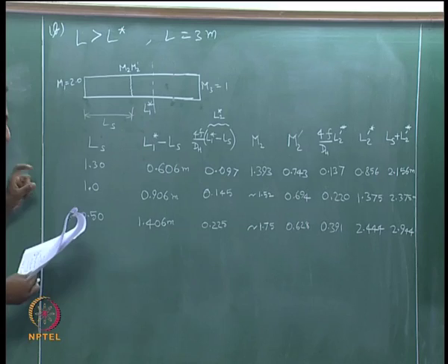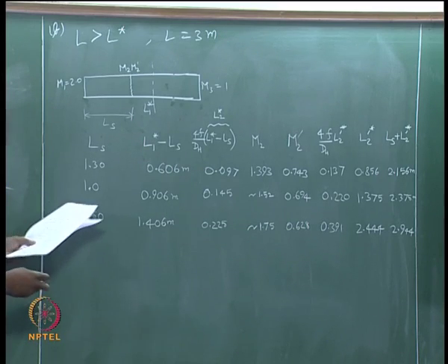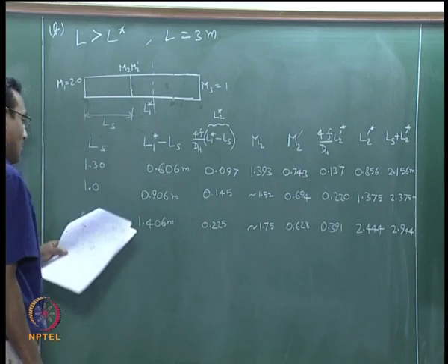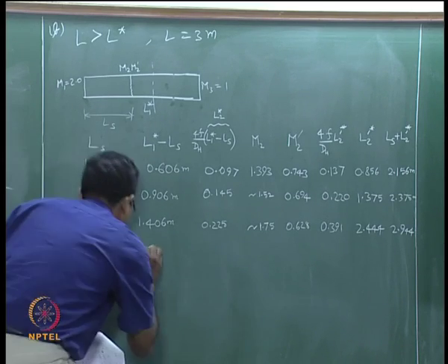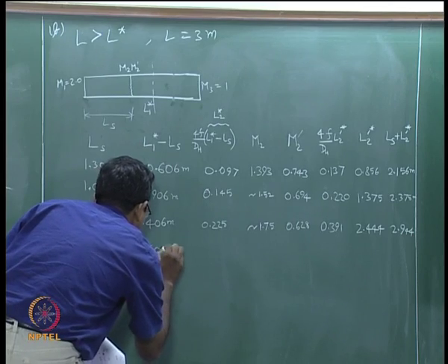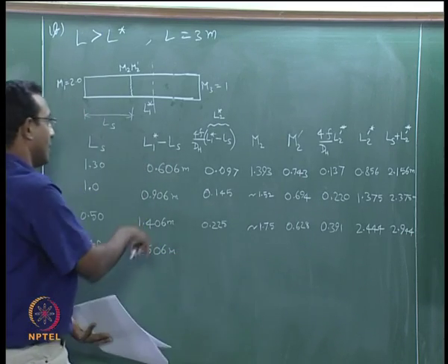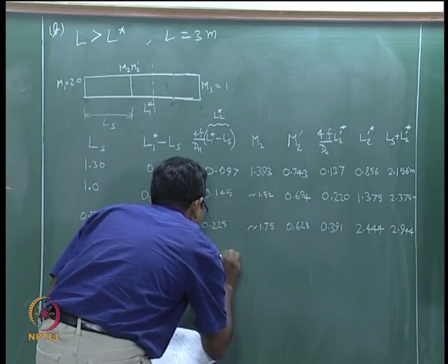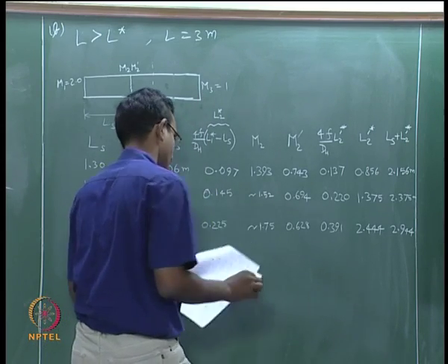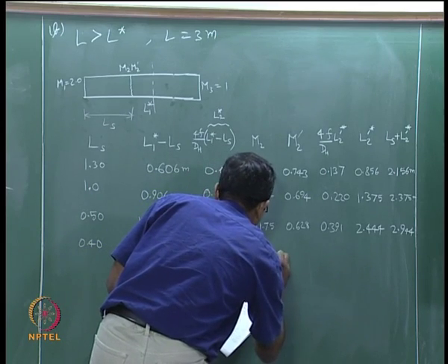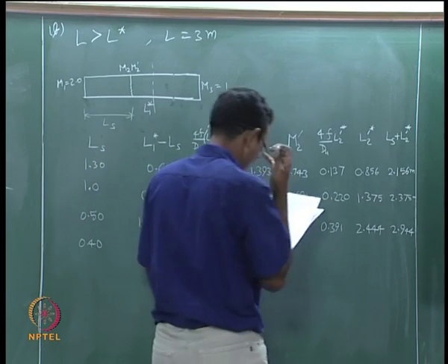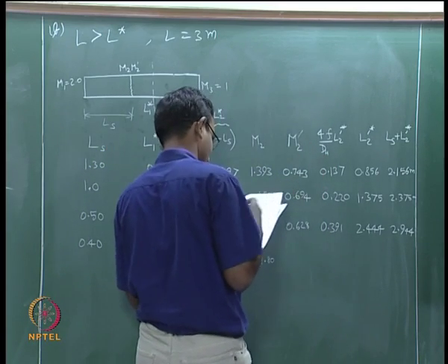So, now I will start changing slowly, I will go to 0.40. That number is 1.506 meters, that I do 4 FL by D, 0.241, and this is approximately 1.80. Till now I am doing only approximately, I will do the better interpolation at the last step.